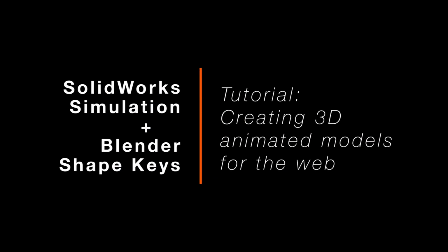In this video, I will show you how to easily animate a flexible part using finite element simulations calculated with SolidWorks and exported to Blender to be animated with the Shape Keys tool.